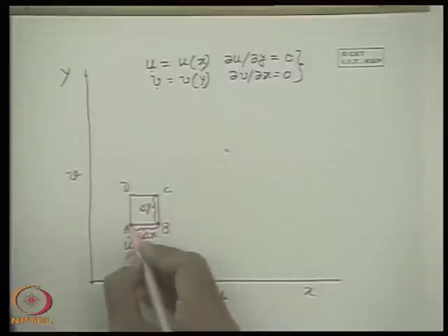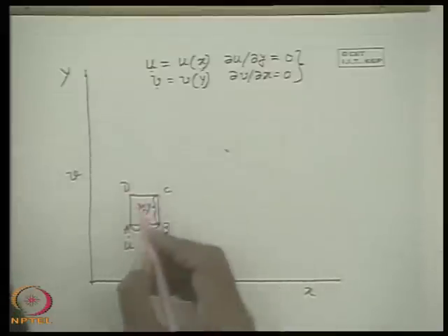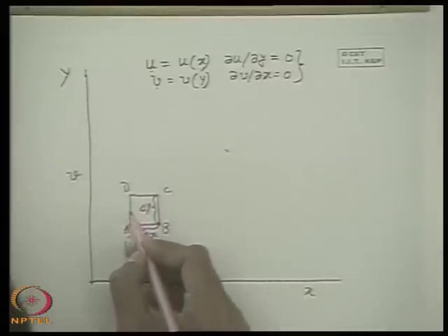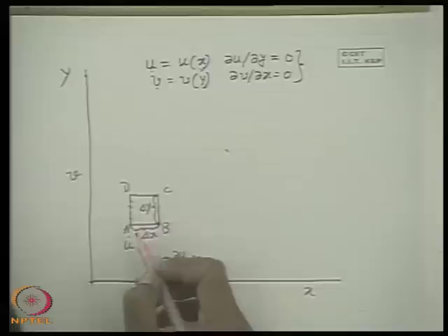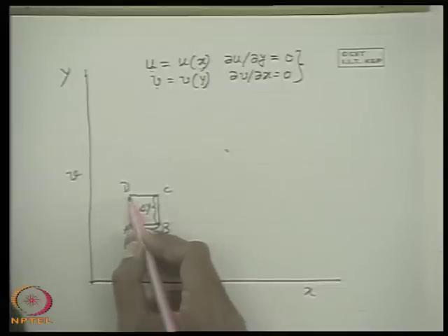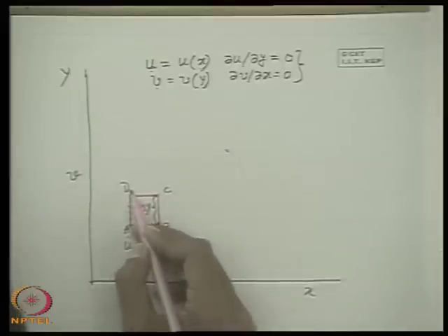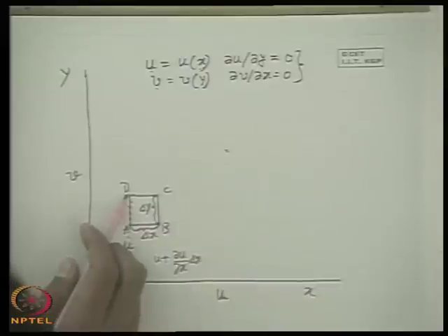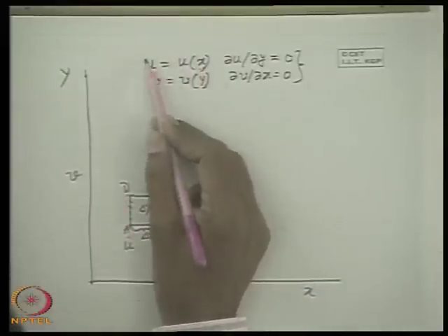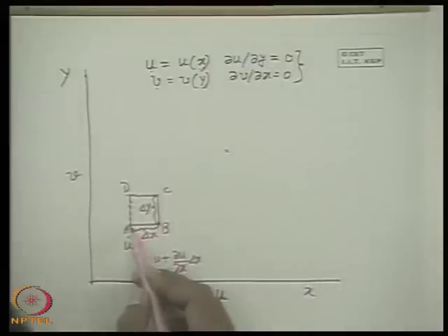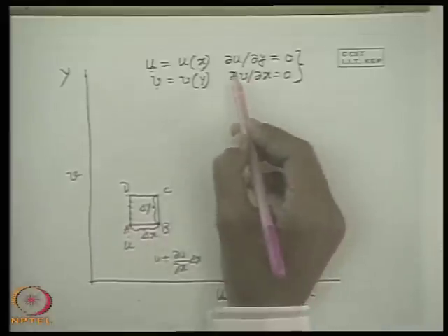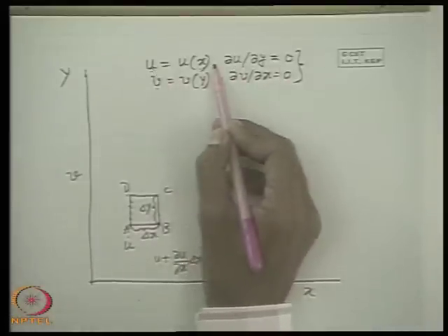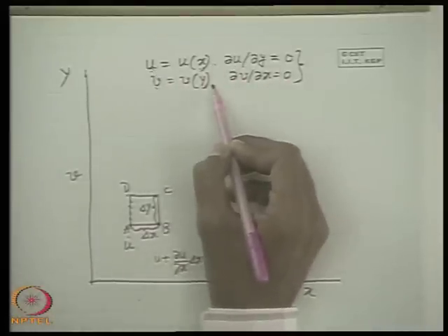So by this, AB linear segments get elongated continuously. Similarly, since the v component of velocity varies with y, each and every point on the linear segment AD, which are varying with y coordinate, has a different y component velocity, which can be told in this way: D point has the opportunity to have a relative displacement over A in the y direction. So this type of velocity variation gives a continuous elongation of the linear segments. But another interesting fact is there, because of this simplification, that u is neither a function of y, nor is v a function of x.